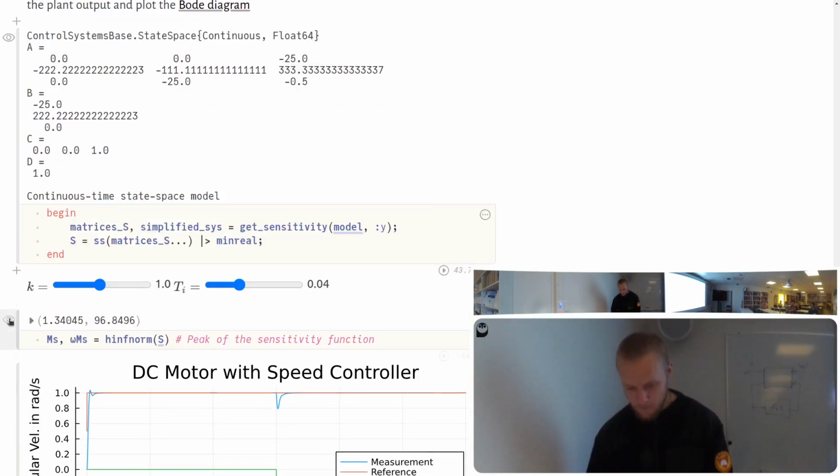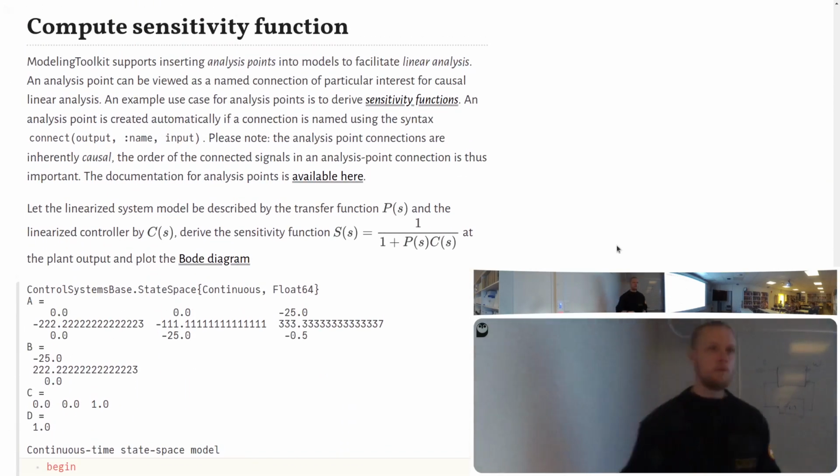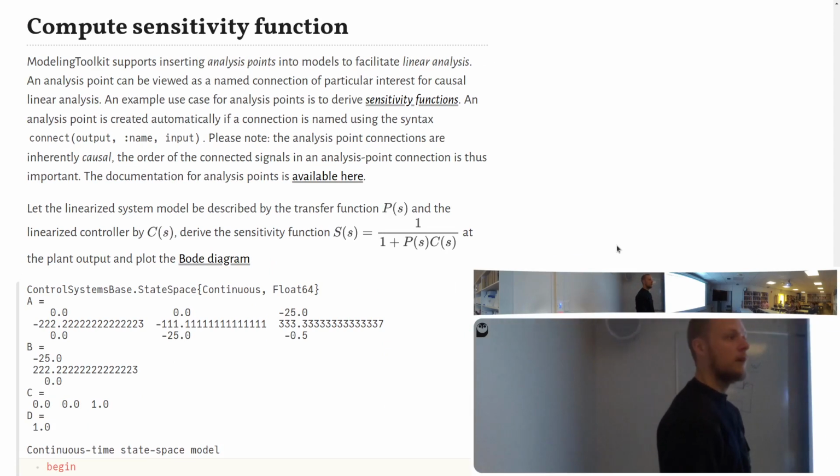The next step is to maybe reason a bit more about the robustness. So we saw a time domain simulation, it looked fine. But before we are happy, we should also check maybe the gang of 4. All right, we should probably always do that.